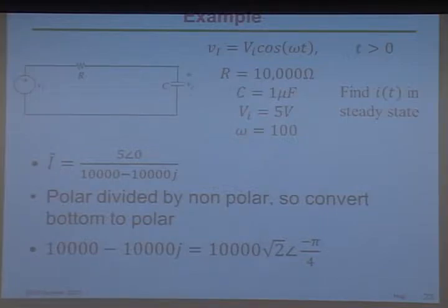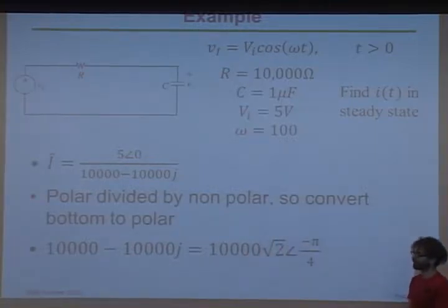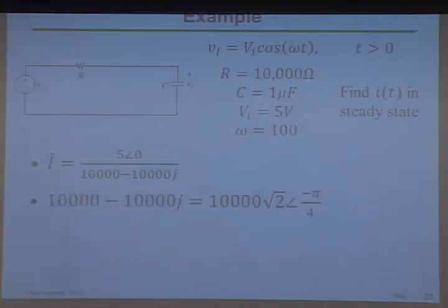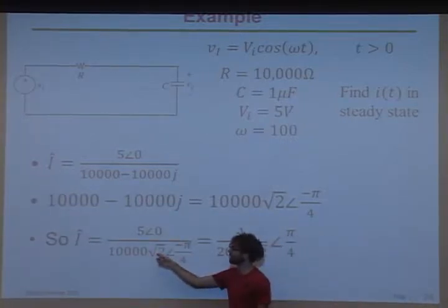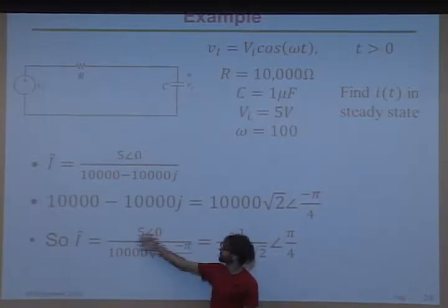So that's going to be our, so what is this number again right here? What's that? The I, V, Z? Yeah, that's the equivalent impedance, right? So once we have that equivalent impedance, what we know is that the phasors are related by the Ohm's law of impedances, so it's just this guy divided by this guy. Why is this form better than the form we had before?